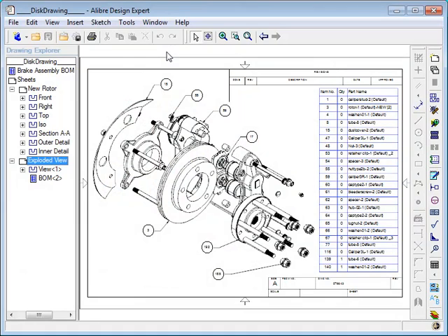Please be aware, the drawing workspace in Alibre Design is not intended as a standalone 2D CAD system. It relies on three-dimensional solid models to produce results. Once you create 3D part and assembly models, documenting them with 2D drawings is simple. In the drawing workspace, Alibre Design projects two-dimensional views of your 3D models. Your primary task is selecting which views you want shown.